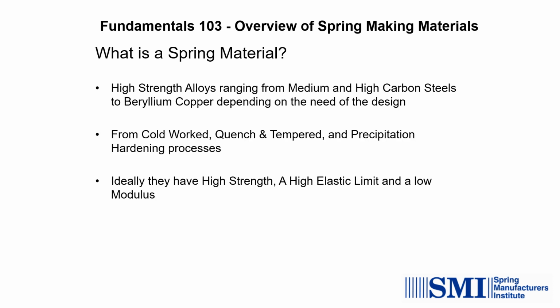What is a spring material? High-strength alloys ranging from medium and high carbon steels to beryllium copper depending on the need of the design. From cold worked, quench and tempered, to precipitation hardening processes. Ideally, they have high strength, a high elastic limit, and a low modulus.